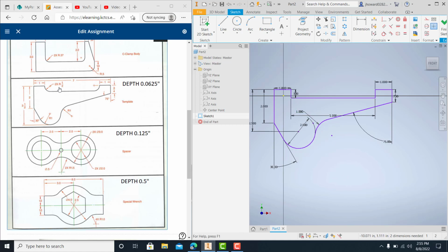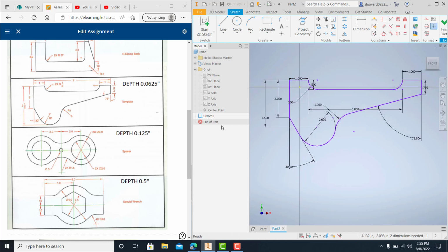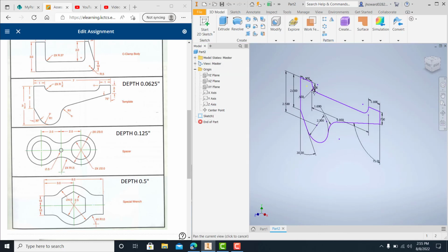But we also got a couple fillets, 1/2-inch fillets up here at the top. We got to do those. So change that to 1/2 inch or 0.5 decimal wise. And there it is. There's your 2D sketch of that. And if you notice something down here, you see that sketch right there in my history as I made it. I'm done. I'm ready to go into 3-dimensional feature mode. So I hit finish sketch. And there it is for us.